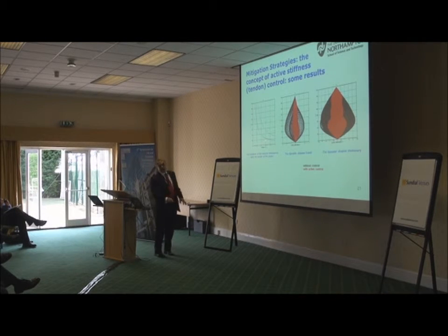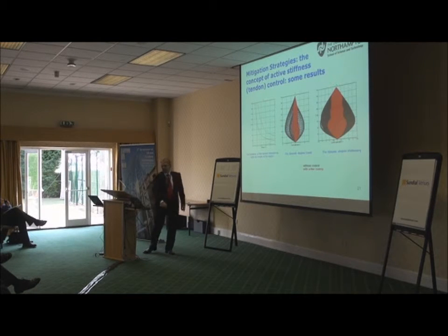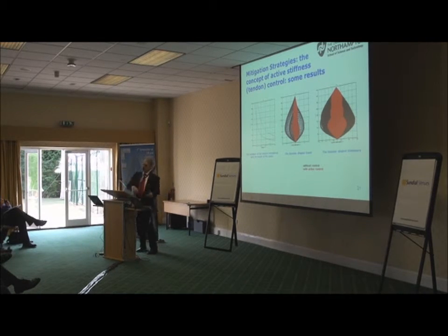Okay, here's an example. This case study comes from numerical simulation. Height of the building, frequency. This is 0.1 hertz. Here's the fundamental frequency of the cable. Here's the second frequency of the cable, because in the cable we actually have plenty of frequencies. What we concentrate on are the lowest ones. At this point, where these lines intersect, we have resonance. And the issue is that at resonance, you see this circular motion.